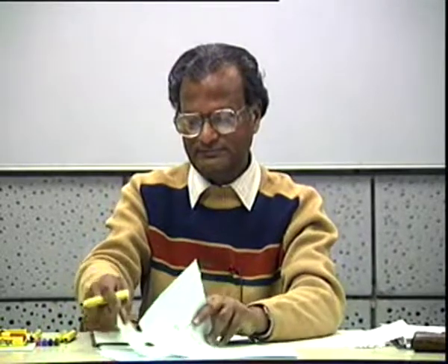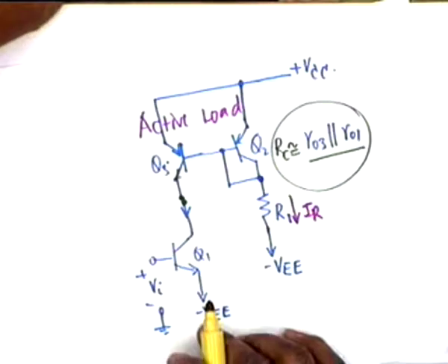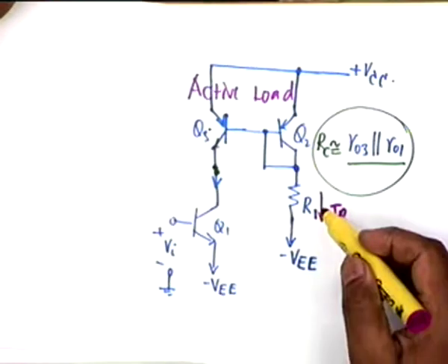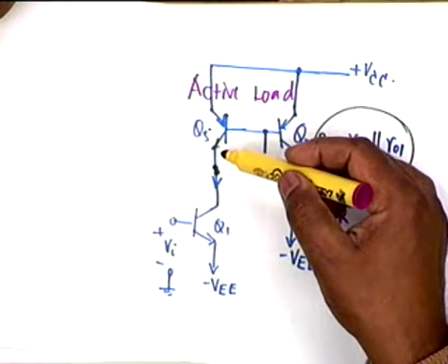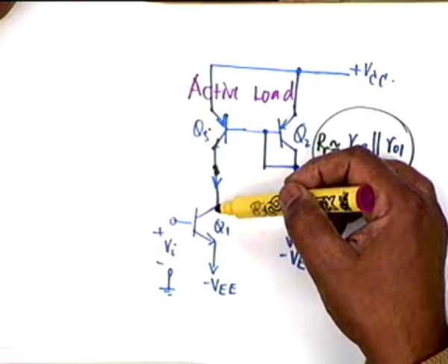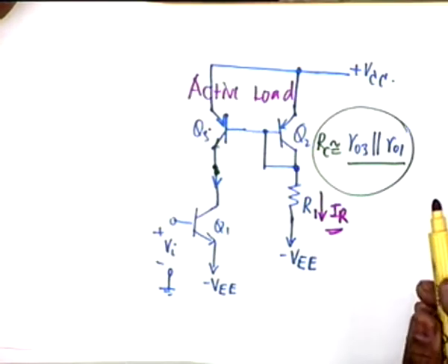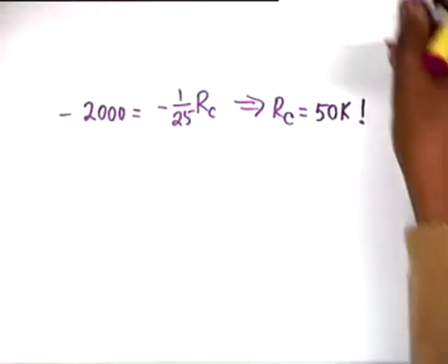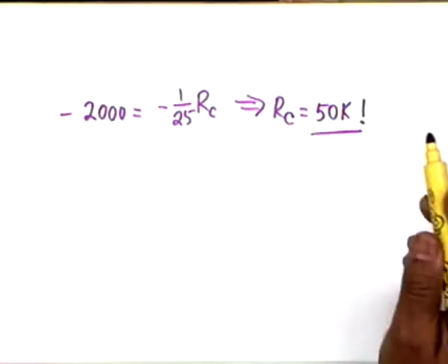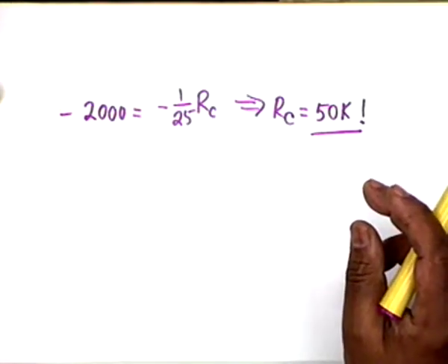I'll just show this. The circuit. Here. This current, IR, which will be approximately the same as IC2, IC3 or IC1. Agree? So this resistance sets the collector current, and what we could achieve by a 50K resistor, we have achieved by using 2 transistors and 1 resistor.